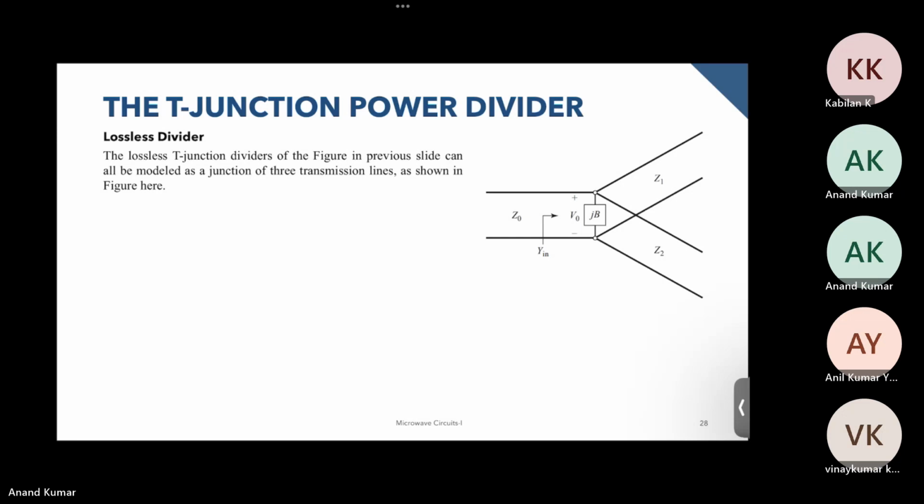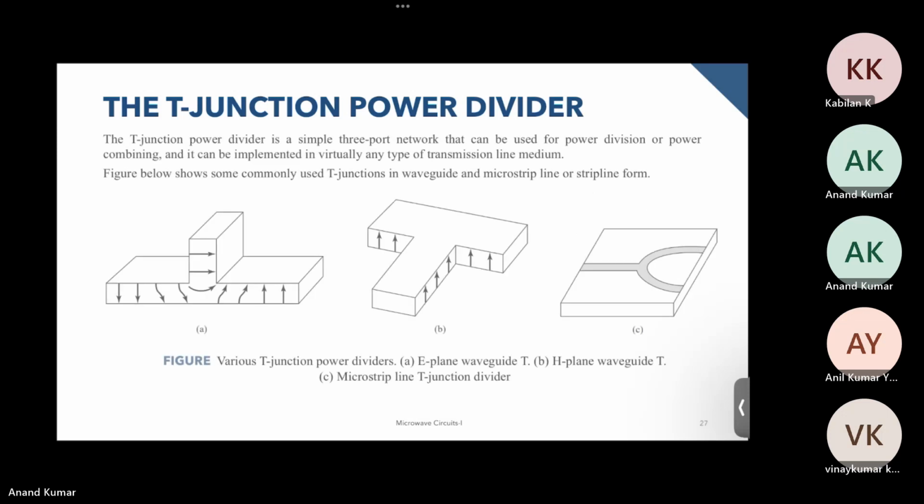Just give me a second. If we have three output ports over here, especially for the microstrip line, we need to divide the power into these three cases. And if you're asking about the S matrix, since there are four ports, this matrix will be 4 cross 4.